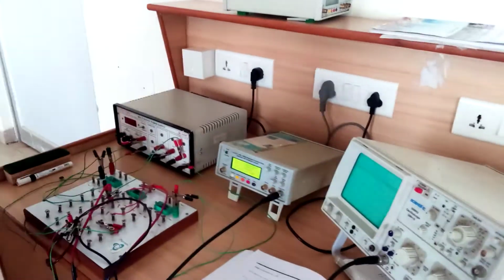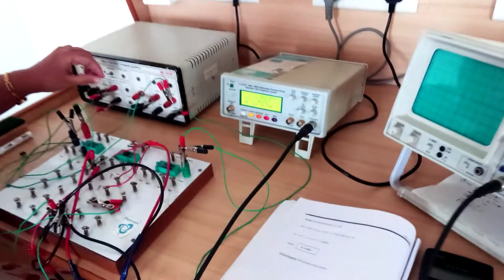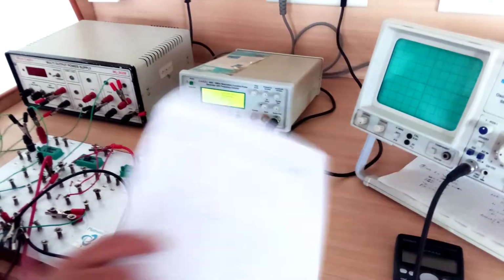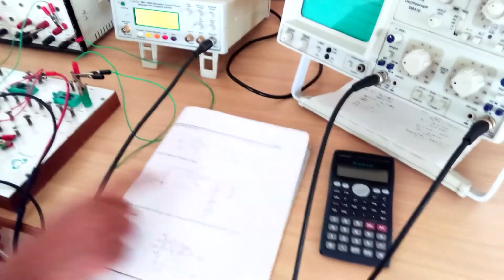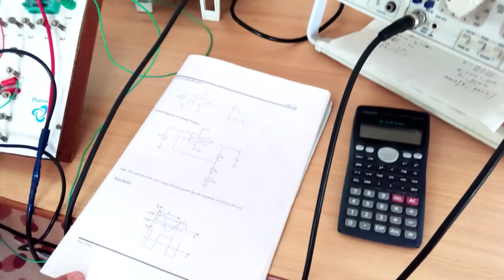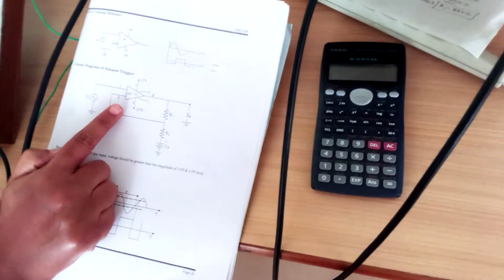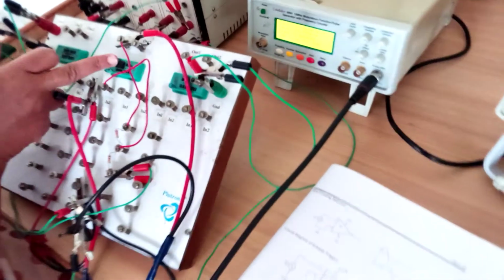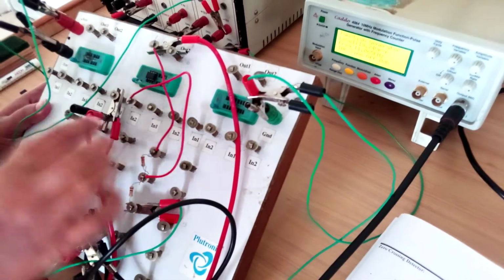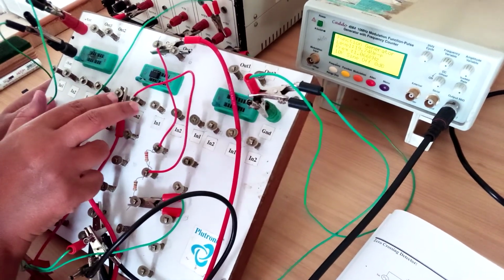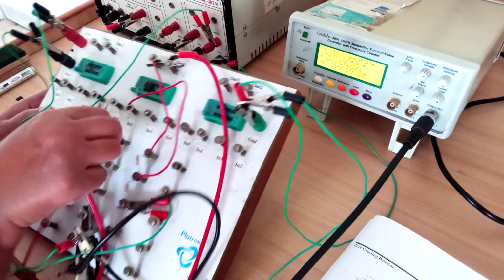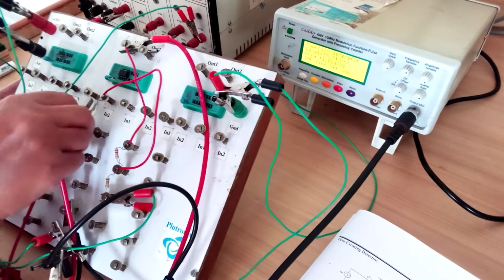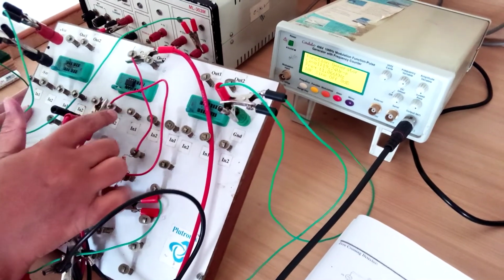So I have already rigged up the circuit. You can observe here, this is the circuit of the Schmitt trigger. So a mu A741 op amp is used. You can observe here I have inserted the op amp in this socket. Corresponding to this socket, the input terminals are these two. On the springboard it will be marked input 1, input 2. So input 1 is pin number 2 and input 2 is pin number 3.